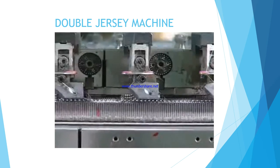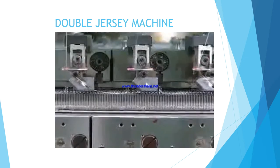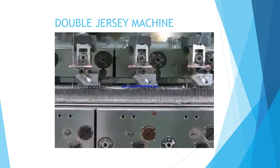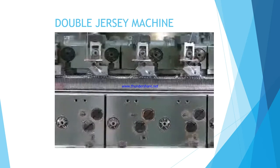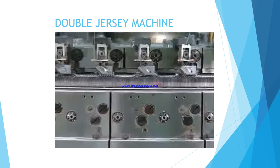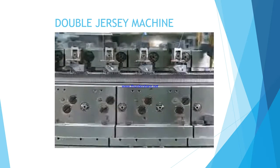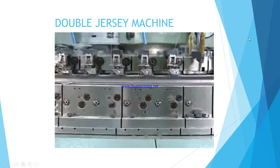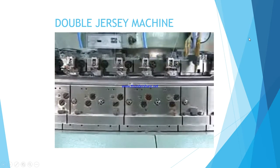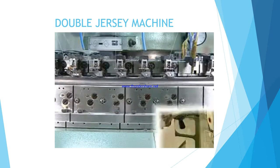When double knit fabrics are produced, the knitting cycles of knit, tuck, and float are the same for the dial as they are for the cylinder. The needles in both the dial and cylinder have butts and are cam activated. Because two sets of needles are used, sinkers are not needed. As the yarns are knit and the fabric is formed, the tubular goods are removed to the inside of the cylinder, as with single knits.